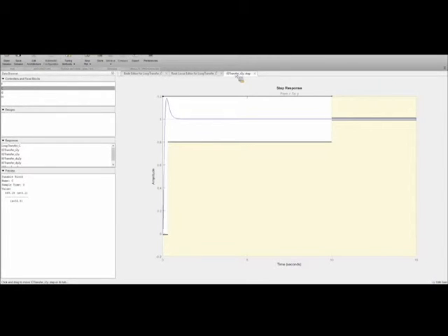Yes, Karsten. Did the MATLAB default pole and 0 locations also distort such that the asymptote was in the acceptable region? So would that be preferable so we don't have such a large gain value? I don't know what it looked like. I wasn't looking at where it was in that configuration, so I'm not sure. But the default is just at -1 and 10. It's very arbitrary, sort of one being 10 times the other one. I would suggest that you probably have to do more than just use the default. Yeah. Okay, any other questions on this before we move on?